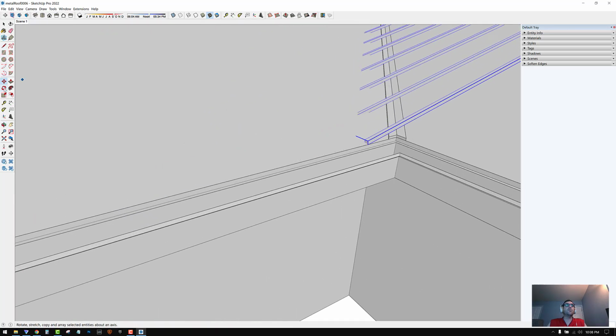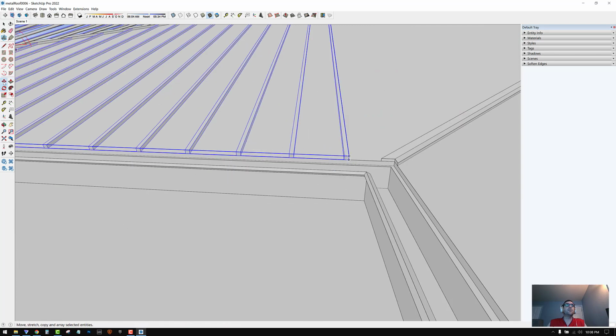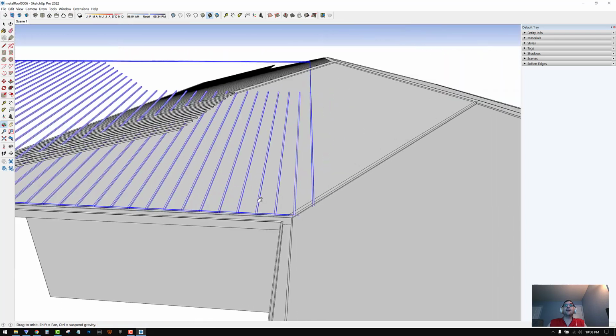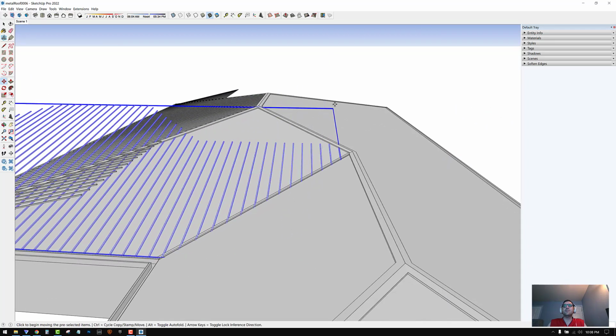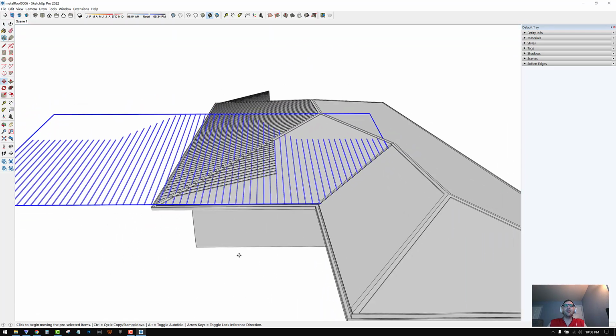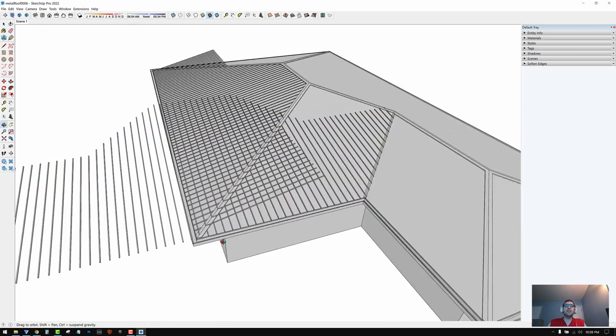And then I'm going to click the rotate tool, click on the blue, rotate it 90 degrees. And then I'm going to move it and hold down Shift to lock it, and then move it all the way over here so that we got that valley covered up with lines. I might just adjust it just slightly like that.